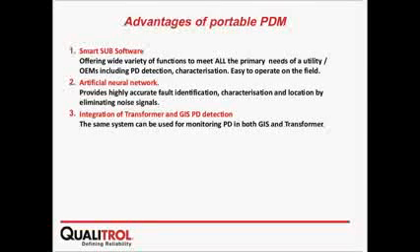So you pretty much get no bias from noise from outside. And then the big plus: the same unit you can use for the GIS or a transformer. Six sensors on a transformer is more than what you need. On GIS, six may not be enough, but for any particular area of concern you have on the GIS, you can leave the unit up and running for continuous monitoring if need be.